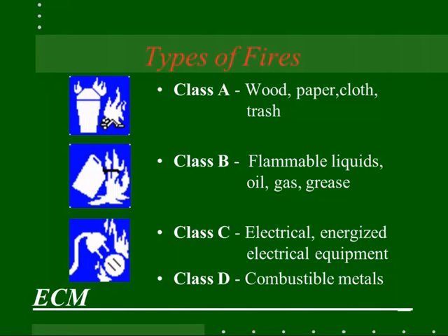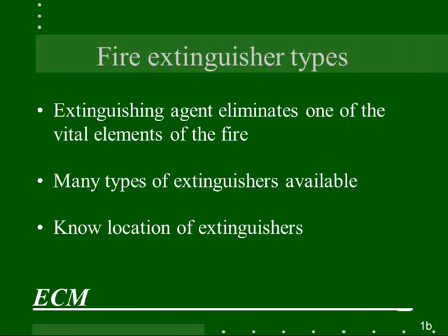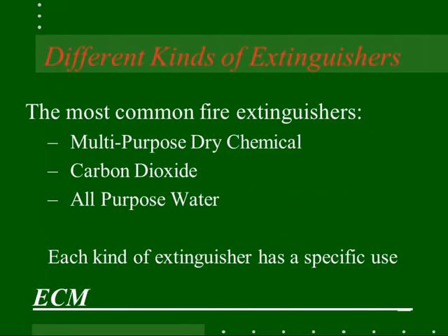Any extinguisher you're going to use is going to have these letters on there, and it's going to tell you which type of fires you're going to put out. So typically, those carbon dioxide extinguishers are going to put out A and B, and those combination extinguishers are going to put out A, B, and C. So again, you're removing one of the sides of that triangle. When you're back in your dealership, you should just take a look around. There should be extinguishers probably every 75 feet or so up on your walls, and those are inspected every year for operation.